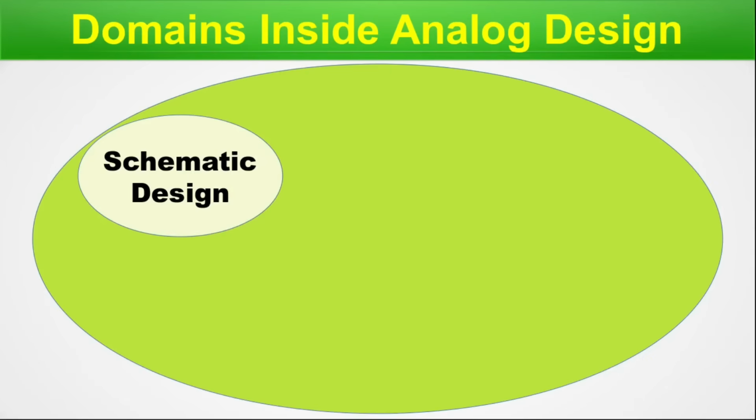Now, let me give some background on why schematic capture is important. In college, when you learned the SPICE language, to convert a circuit diagram into SPICE you had to mark each node by hand with a particular number. Then you had to use a text editor to write the .cir file. This is good enough for college-level small circuits, their design and analysis. But when we do large designs in the VLSI industry, this is not a very fruitful method. So we need some method which is far more efficient for industry-level analog circuit design.